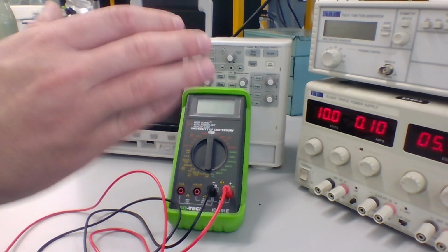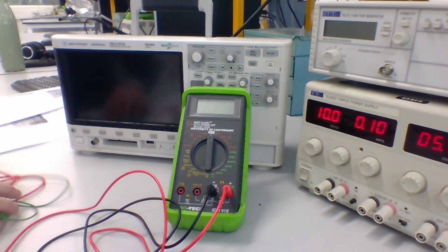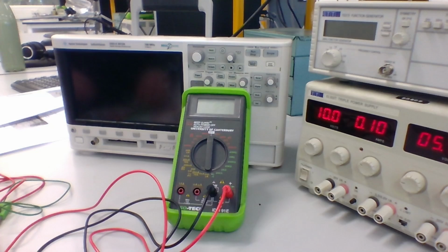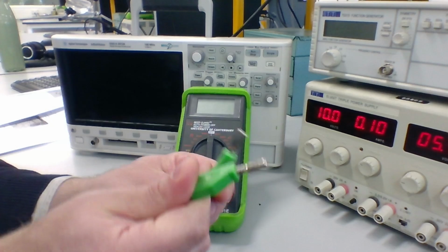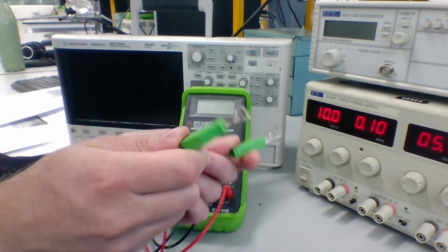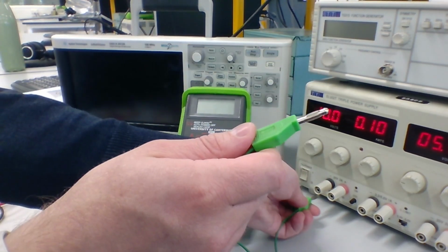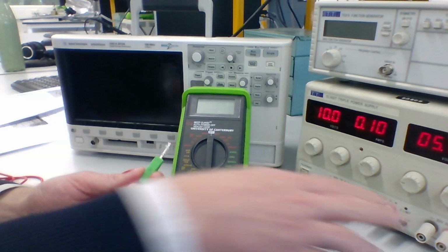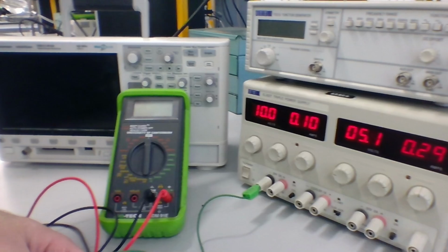Okay, now that our power supply is set up, what we want to do is grab some more cables to connect our power supply to our resistor. What I'm going to do first of all is grab a banana to banana jumper or wire like this, and I'm going to use this to connect the black negative terminal of this power supply into the earth connection on this power supply, which is on the right hand side over here.